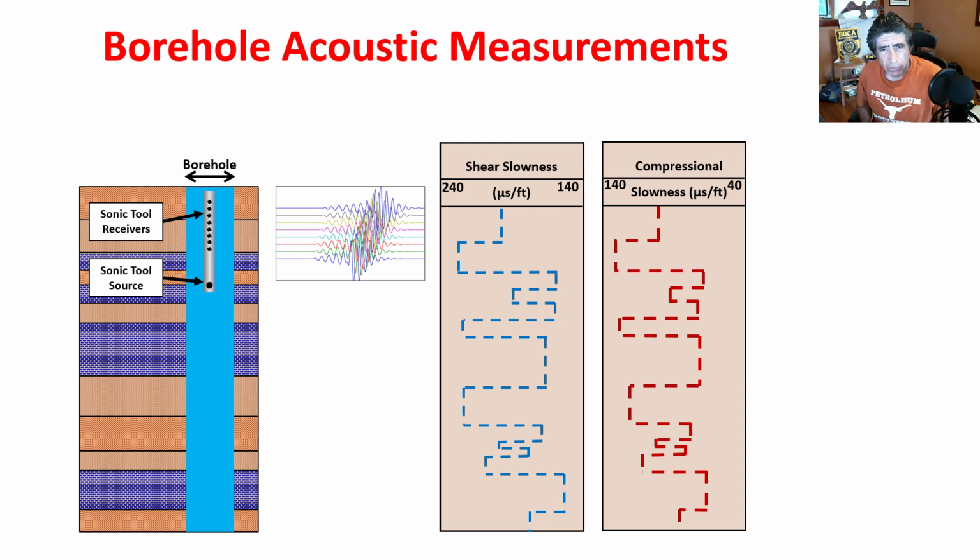And here is how things work. When you do a borehole acoustic measurement, sonic logs, we're actually sending an acoustic signal coming from the borehole. The tool is immersed in the borehole, the tool is moving, and those signals are being sent. And what we measure is the time of flight that it takes for those measurements to happen.